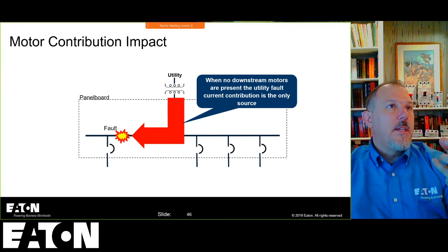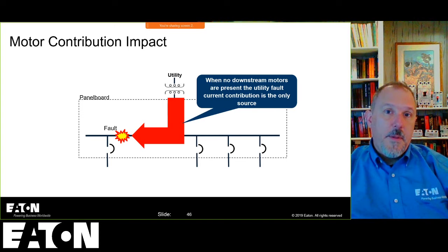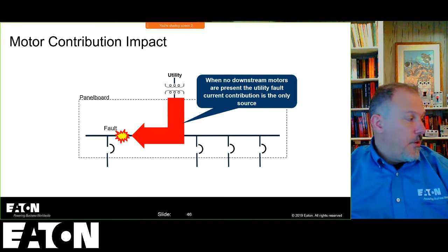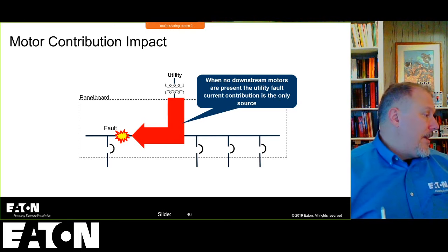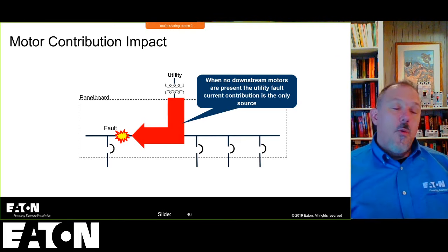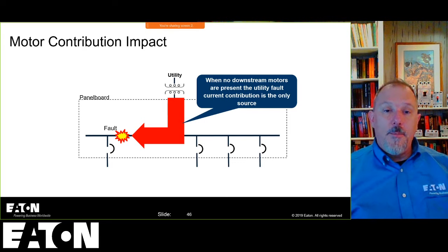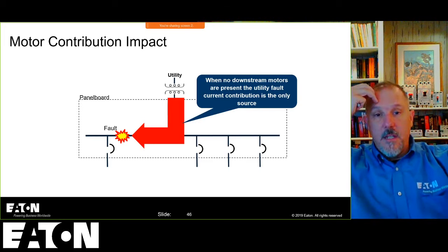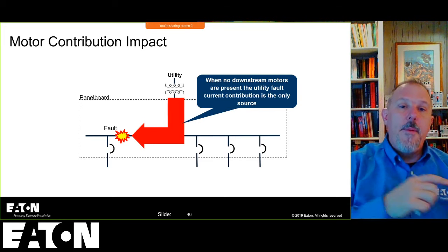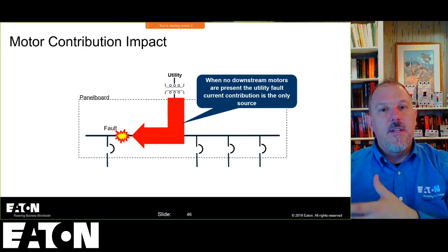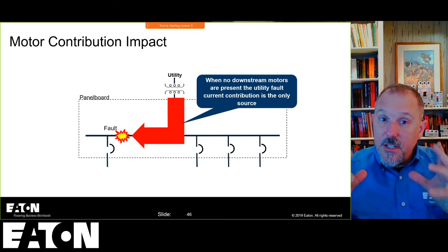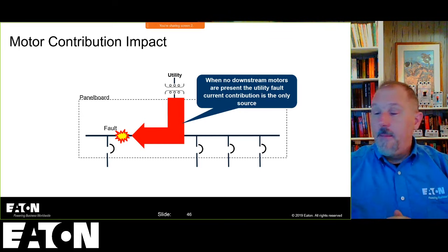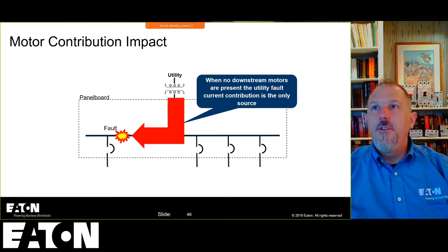Putting a date on the label is an NFPA requirement, isn't it? No, it's not, Henry. It's not an NFPA requirement. Only if you're in 110.16, we talked about this earlier. 110.16, if you do the option that's in the parent text of marking the fault current, marking the clearing time, etc. If you fall back on an industry practice, which is falling back on 70E, 70E does not require the date on that label.